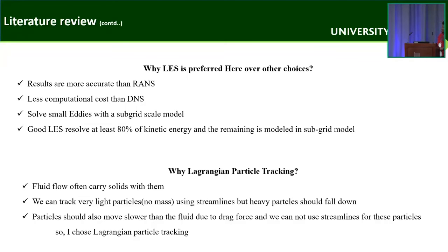Why Lagrangian particle tracking? Basically, fluid flow often carries solid particles with it. We can track very light particles using streamlines, but heavy particles should fall down. Particles should also move slower than the fluid due to drag force, and we cannot use streamlines for these particles. And so I chose Lagrangian particle tracking.